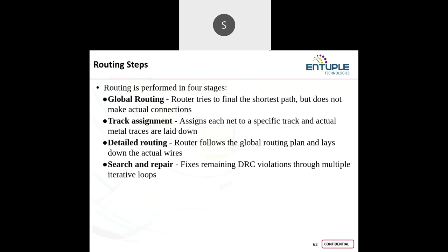Usually there are two stages. One is initial routing, where the connected nets are routed, and any overflows with the G cells will be calculated here. Another one is the rerouting stage. Here in the rerouting stage, where congestion is oriented with the G cells, any net overflows will be reduced by ripping up, or you can say by rerouting the nets. By rerouting the nets, those violations can be fixed in global routing.